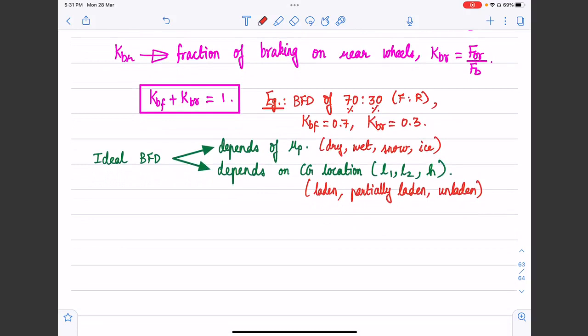To avoid what is called wheel lockup. Because if we apply too much brake, more than what can be sustained at the tire-road interface for a particular operating condition, we have locking of wheels, and that is something which should be avoided. In that context, we will look at ABS shortly. But before we go to wheel lockup, any questions on what we have learned till now?